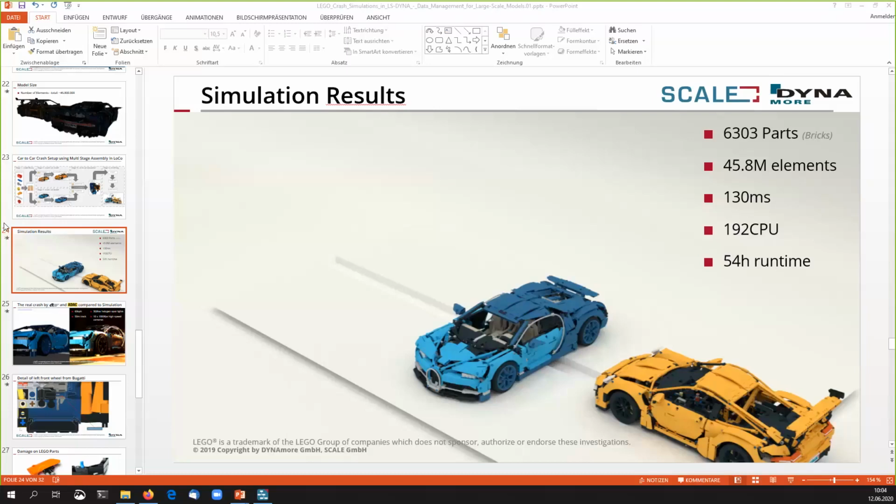I have a question, Marko. Did you use any special decomposition technique here to reduce the runtime, or did you use the standard LS-DYNA decomposition technique? Actually, at the beginning, I used the standard LS-DYNA decomposition technique, and then Pierre from France introduced some keywords so that the decomposition was just in one direction to get a better behavior.